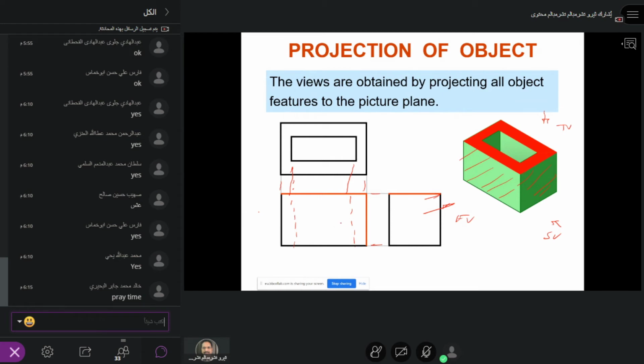So when I see this dotted line, it means I am trying to represent there is something, what do you call it, hidden. So I have to see the top view and compare these two, then I can visualize, okay, there is a projection like this and this is what this hidden line shows.